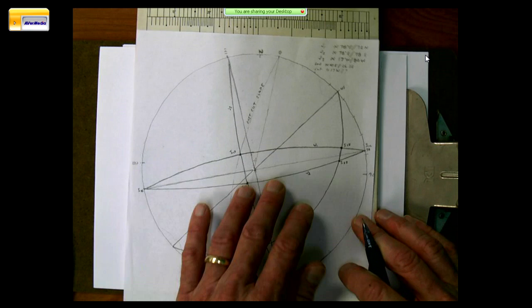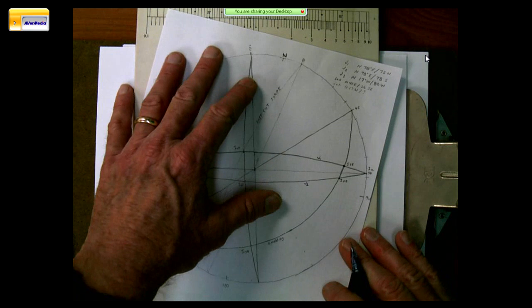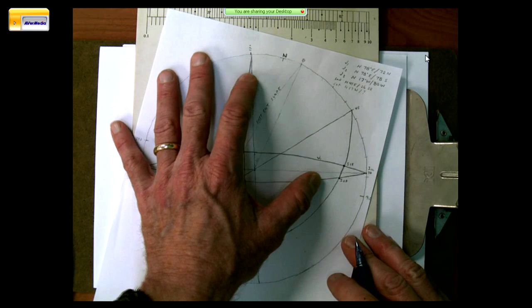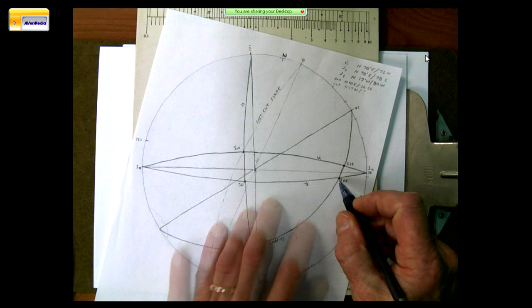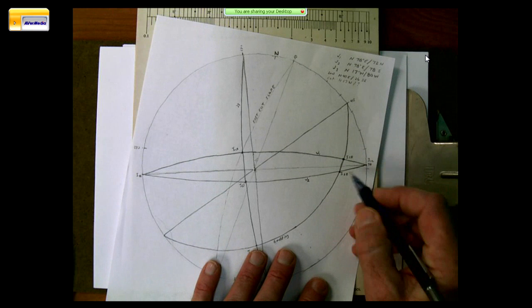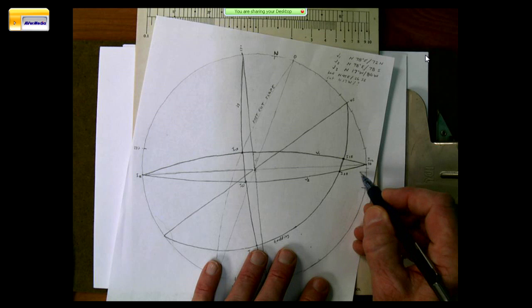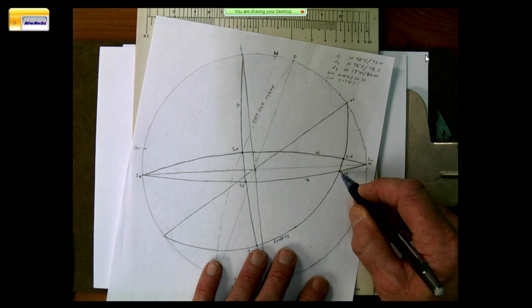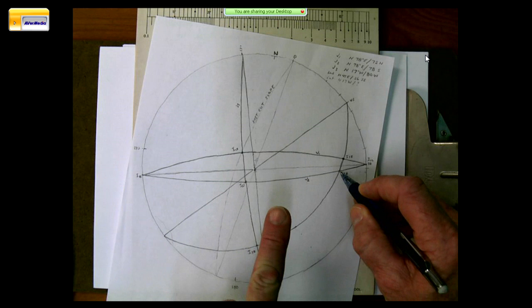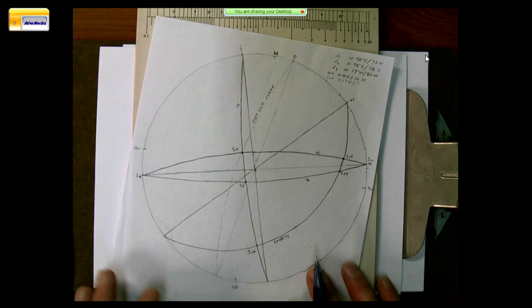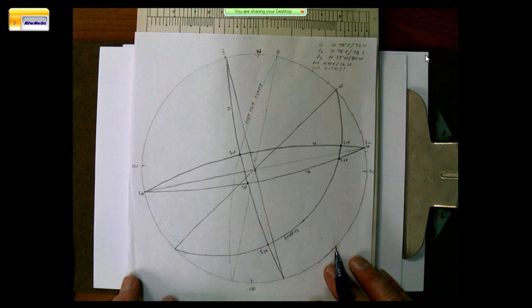And if I rotate this again, I can actually see, if I bring this point to the equator line, the east-west line, what I can see here is that's 10, 11, 12, 13, but it's dipping, that intersection is dipping about 16 degrees. That's pretty flat. It's going to be hard for that wedge to slide out unless the phi angle is less than 16 degrees. So not going to be too problematic.